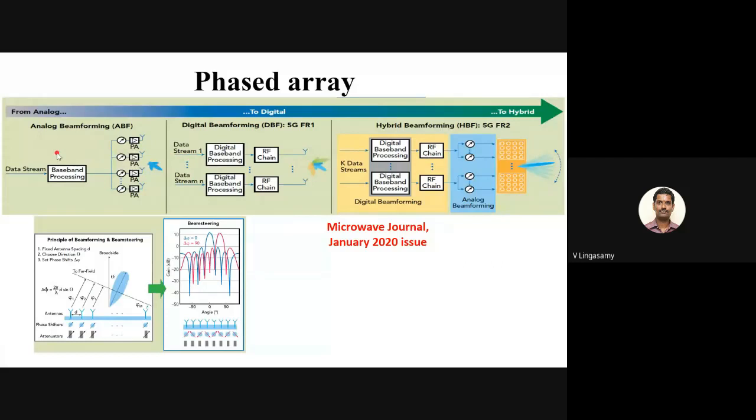So, to get the advantage of cost reduction and compactness, as well as multiple baseband processing, we go for a hybrid processing technique, where digital processing is there individually, and some of the RF chains are split into multiple RF chains and then connected to the massive MIMO radio. But in general, massive MIMO uses digital beamforming. Very rarely do they use this kind of technique.